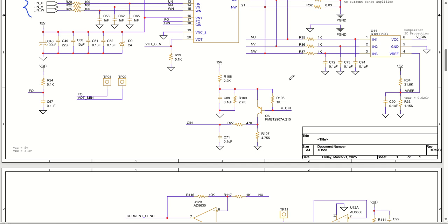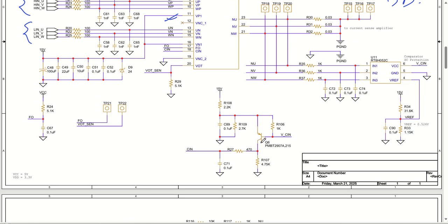This is a transistor based driver, a P type transistor based driver. Then this is going to come up here as CIN, and this CIN is going to get connected. So, understood the process? This current sense resistor for short circuit protection goes to this comparator. The comparator output will come here, and this is going to drive CIN and then get connected at this place.